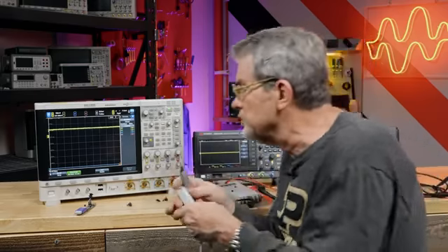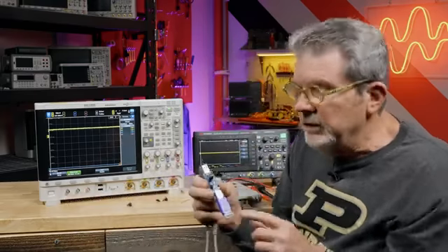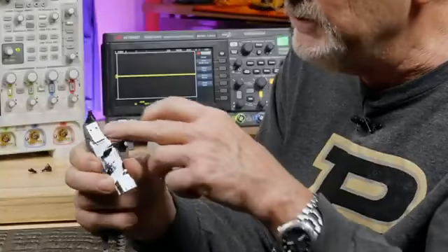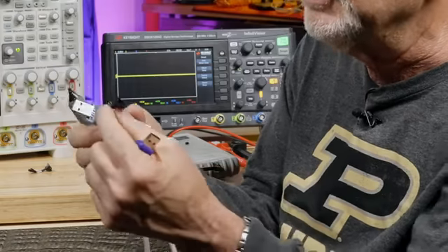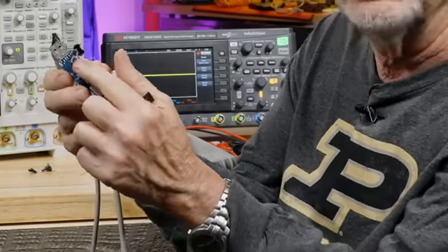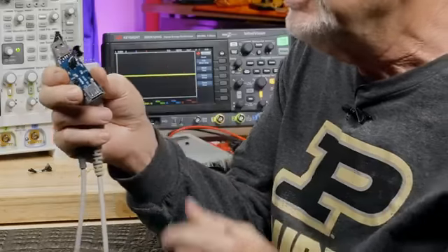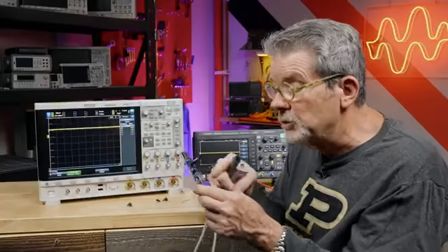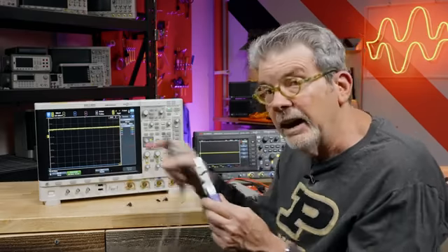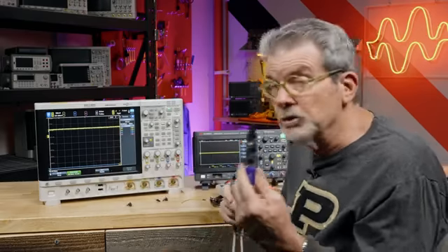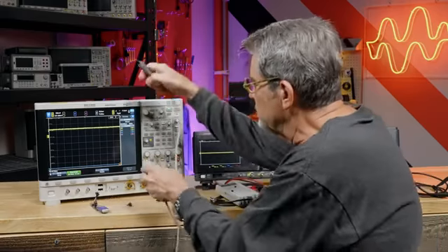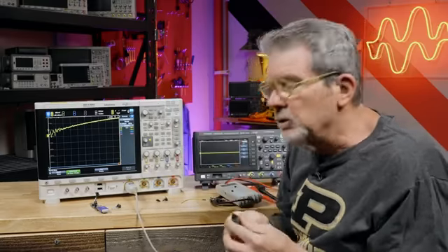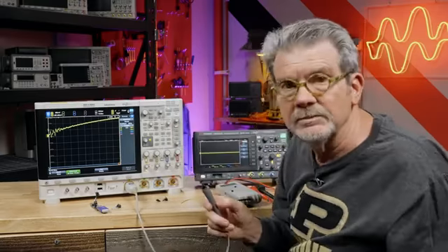And so I'm going to demonstrate something to you. What we're going to test is signals coming out of my USB drive. We have a special fixture we made here. This is my probe tip that's got the socketed connection. It's connected to a couple of header connectors. And we're going to look at the signals going in and out between my USB drive and the oscilloscope, and we'll see how fast they are. So let's first of all plug in the probe, and then we'll connect the probe to the DUT.